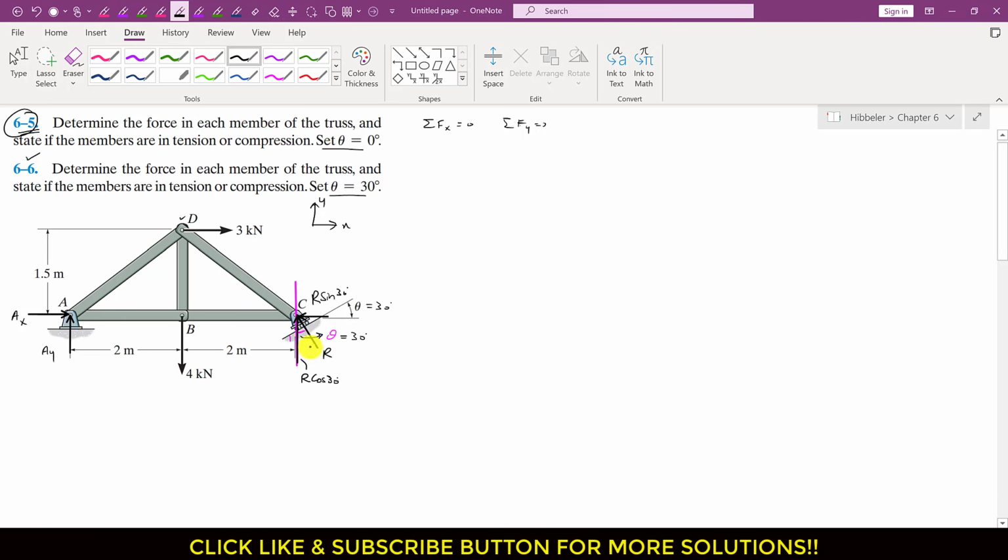We have two components of this R, right? So now first what I will do is that I will consider this whole truss, and I will apply the summation of moment about point C equals to 0, and we will assume that the counterclockwise moment is positive.